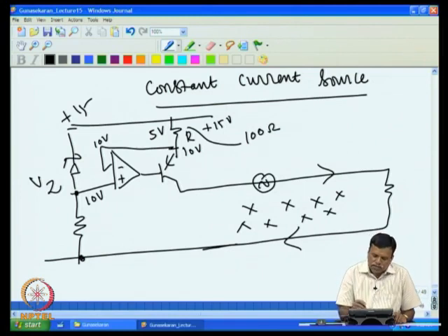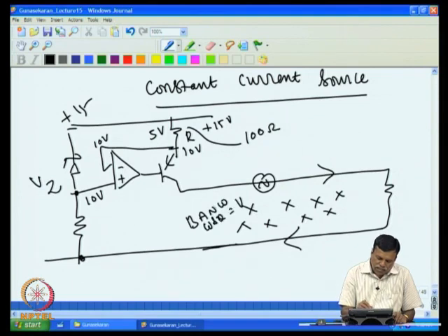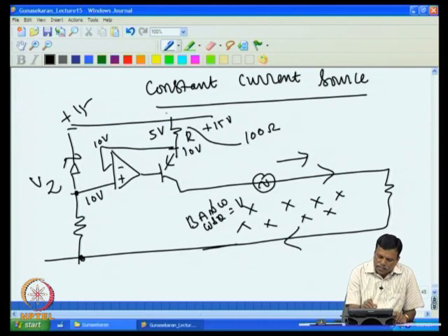This voltage is an AC voltage, because we know that B A n omega cos theta is the induced voltage, and here n is 1. So the changing magnetic field induces a voltage here, and this AC voltage will not drive any current through this, because if this voltage drives a current through this, that current has to come from the supply only, and that current has to go through this. There is no way this induced voltage can complete the path through the current source.